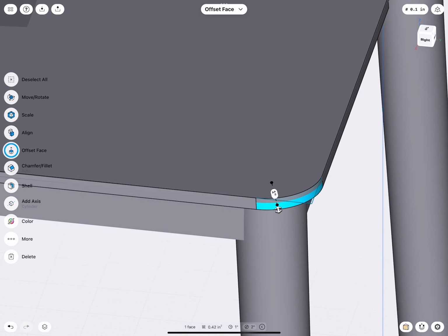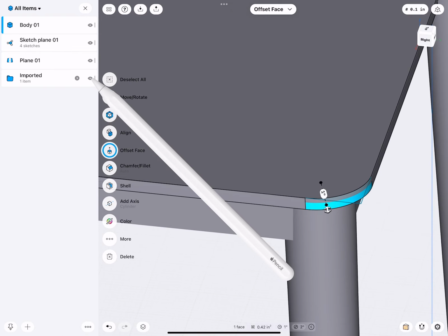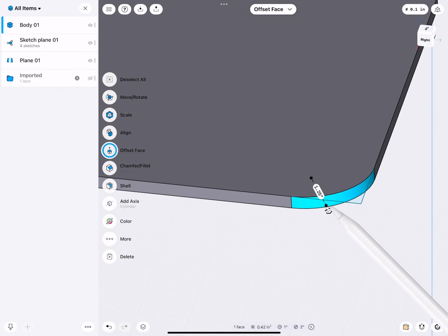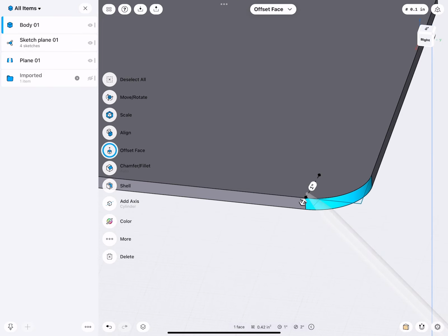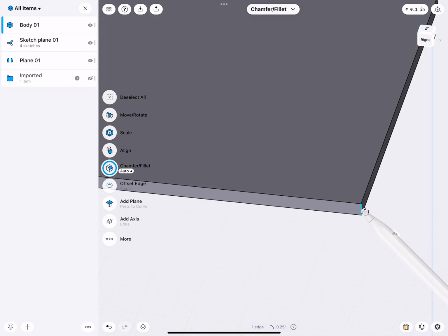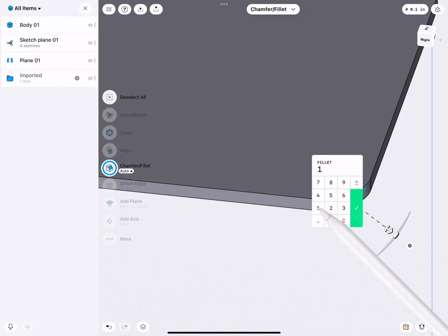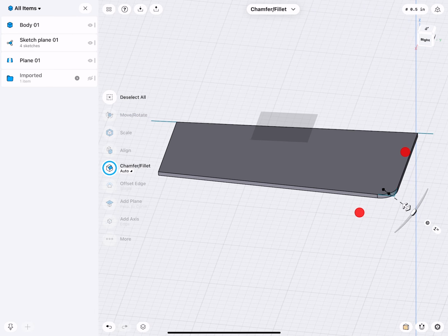What's really nice about this process is, because this is just part of the geometry, I can always later select it, very quickly adjust it. Or I can delete it and bring the fillet back. In my professional practice, I find it very easy to work with very simplified sketches. They're more manageable. And then I offload specific tasks like fillets to solid modeling, where it also seems to make more sense and is more fluid.